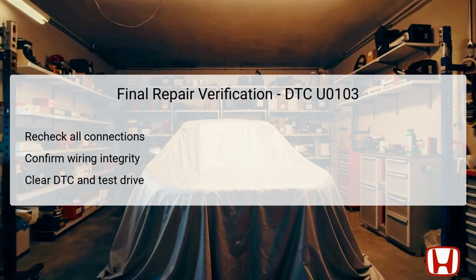Once you are certain that all repairs were conducted properly, use the Honda Diagnostic System, HDS, to clear any DTCs from the memory. Following this, conduct a test drive under various conditions to confirm that the issues have been fully resolved and the DTC does not return. This comprehensive approach ensures safety and reliability in the vehicle's operation.